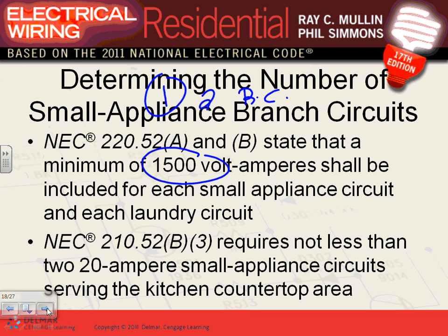So, Phil, my friend, when you get into your kitchen, at least you need to have two 20 amp circuits that feed all the receptacles in the kitchen and the dining room, if any. You can have at least two, and they're all 20 amp circuits. And if it's a 20 amp circuit, what wire do you need? Number 12. Number 12, that's a must. That's a place where you have to use number 12. You have no other option. Number 12. Any question, guys, about this?